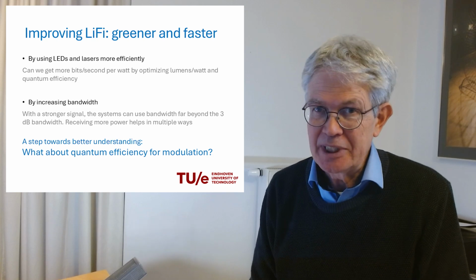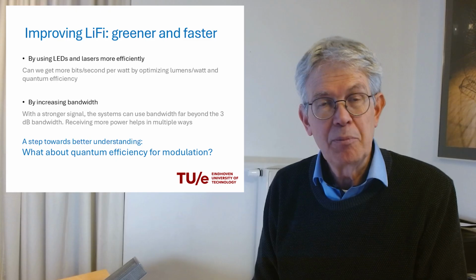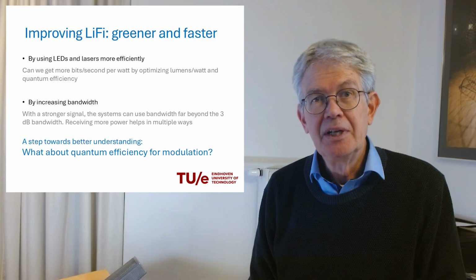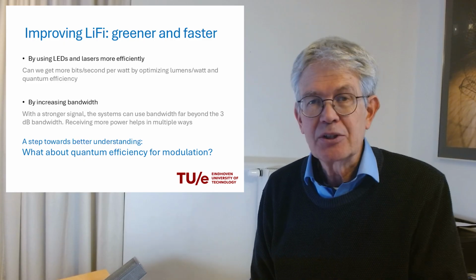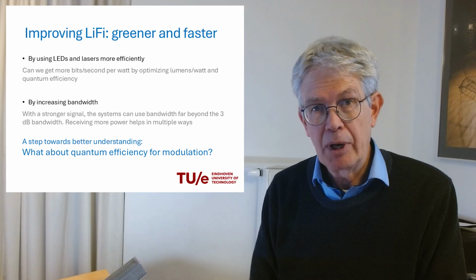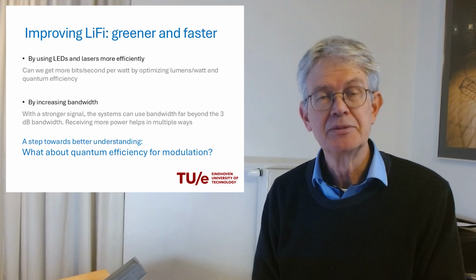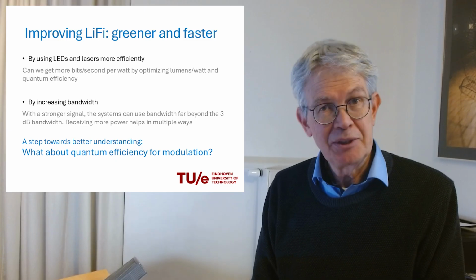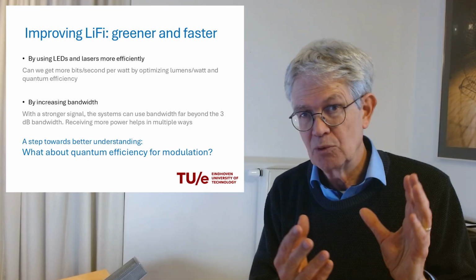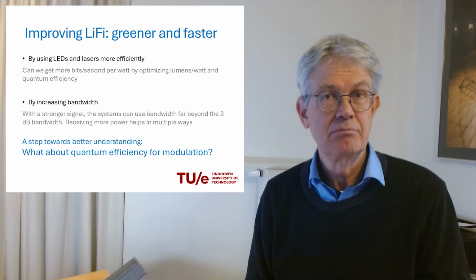We like LEDs because they are very efficient. And in illumination, almost all incandescent bulbs have been replaced by LEDs because of their efficiency. For every watt of electrical power that I feed in, I get almost a full watt of optical power out. Their efficiency is high in terms of what's in, what's out, but also in terms of quantum efficiency. Almost for every hole and electron that recombine in the electrical part of the LED, we get a photon out.